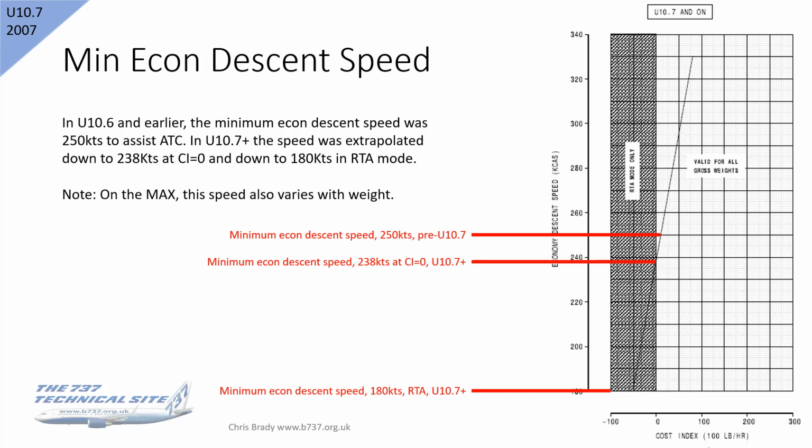In RTA mode, it doesn't matter, because we use this if we're told to expect a delay at a certain hold before, or to meet an RTA, then sure that air traffic are expecting you to fly whatever speed you need to achieve that. But just be a little wary of cost index 0 post 10.7.